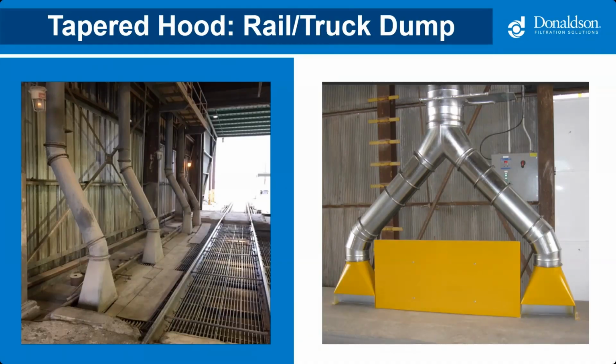Here are examples of tapered hood used in rail and truck dump pits. Dust generation is highest when the gate is first opened on the bottom of a hopper trailer or rail car. You always want to fully open the gate to choke feed the dump pit.